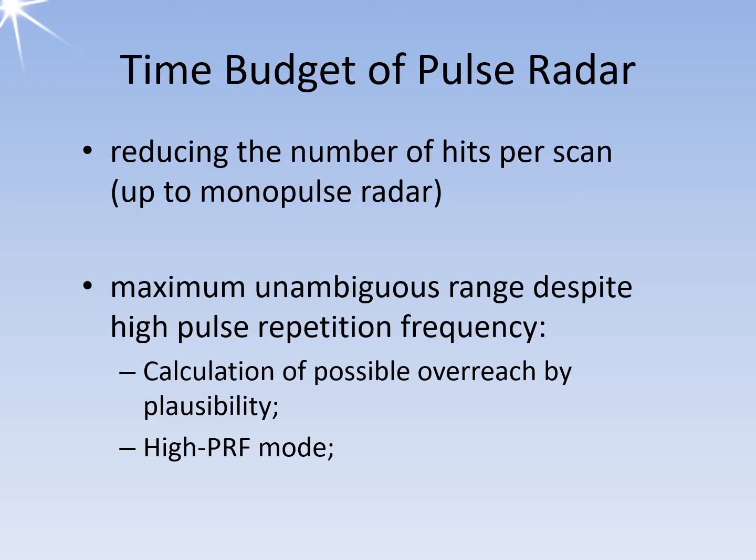The radar can then computationally add the time of the empty pulse periods to calculate the runtime for about 800 kilometers. For adjacent points on the Earth's surface, a jump in the measured distance of 40 kilometers difference is unlikely. This mode of operation is called high PRF mode.